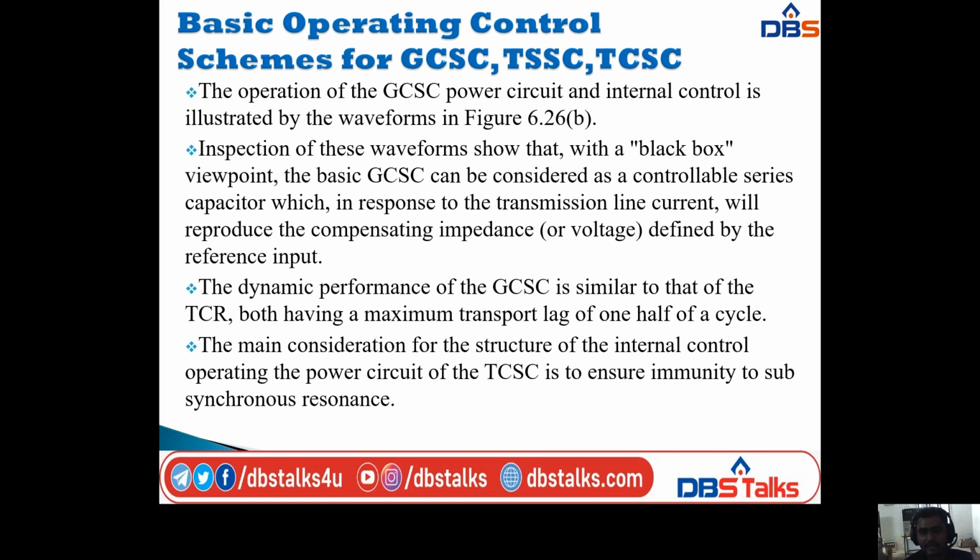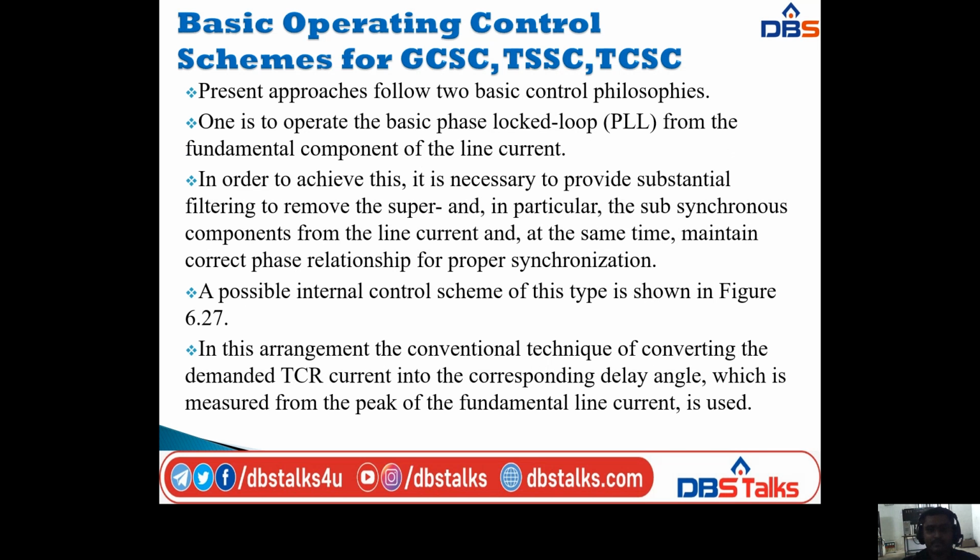Both have a maximum transport delay of half a cycle. The main consideration for the structure of the internal control operating the power circuit of the TCSC is to ensure immunity to subsynchronous resonance. And so present approaches follow two basic control philosophies.